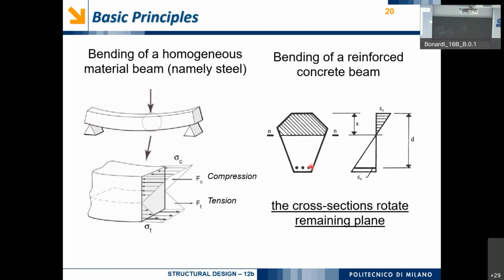And if we know the constitutive law of the steel, we can recover the level of stress knowing the strain. So we just integrate some stress that will be computed in a different way from what we do in the concrete, and we can find the tension force that is capable to counteract the compression force in the compressed part of the cross-section.